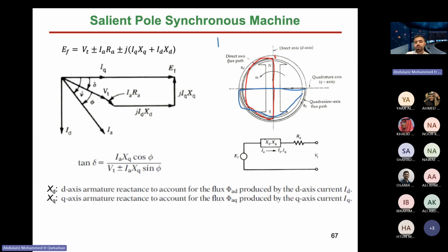If you recall from last lecture, reluctance is G, the effective air gap, over mu A. Of course, you consider the reluctance of the air only. You don't consider the reluctance of the steel, because you assume the steel would allow the flux to go. So your point of concern is this gap, this gap, this gap, and this gap. Clear?